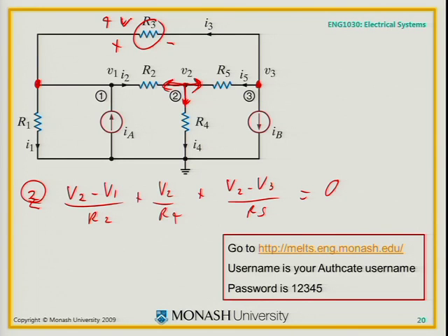Excellent. Remember, this was V1 here. From there, this is V3. So V1 minus V3 must be 4 volts. There's one of my equations. There's one then slight trick. We've still got to apply Kirchhoff's current laws. And for that, we're going to apply it at something called a supernode. Not just at a node, but a supernode. That's going to have to wait till the next lecture.